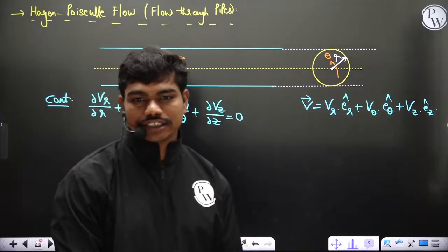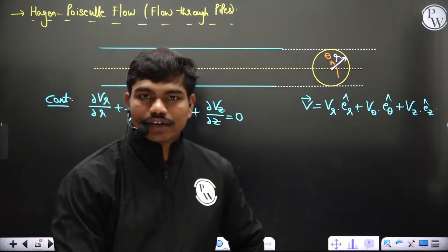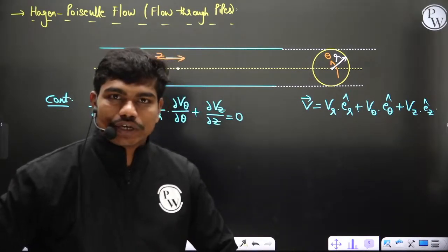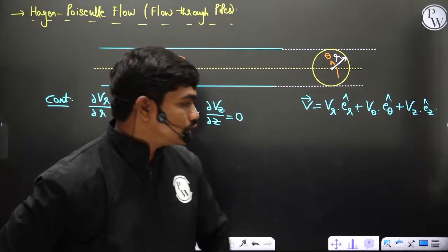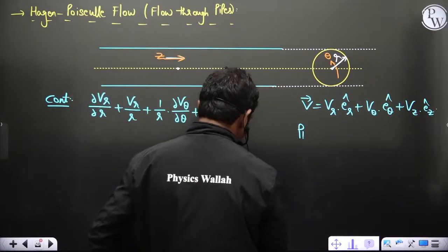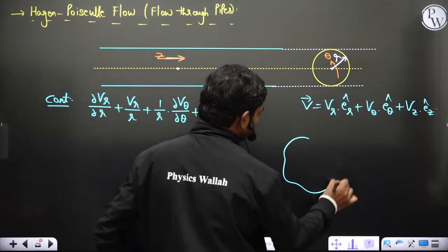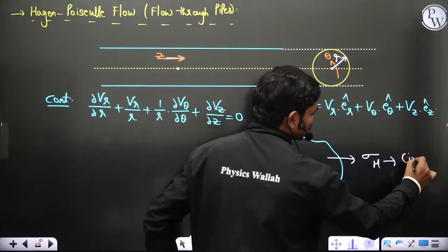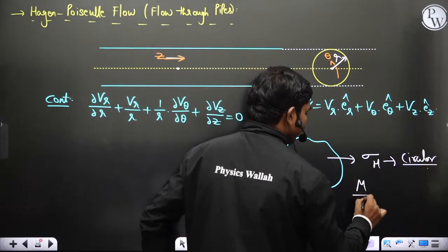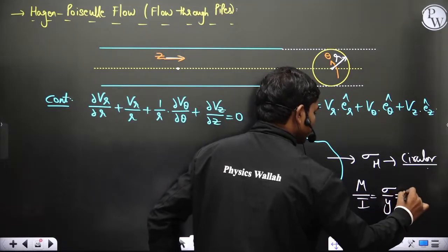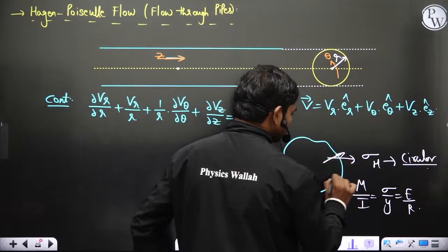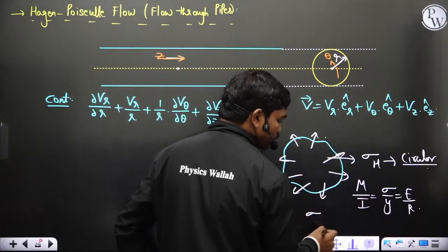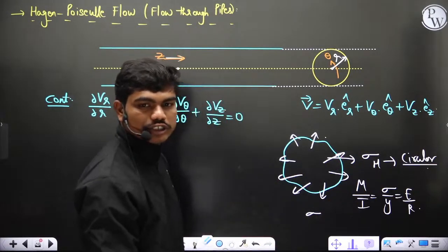Pipes are circular for a reason: stresses, basically hoop stress, is the reason. Right now I may not explain it, but you can ask in machine design or in strength of materials. Normally if you do the stress analysis, you know the hoop stress, right? For any random cross section, the hoop stress management is better for circular. You can see this derivation using this equation. This is of course for bending. Whenever a certain pressure is exerted like this in all the cases, and if you apply certain values, you will find out circular cross section is the optimum cross section in that case.